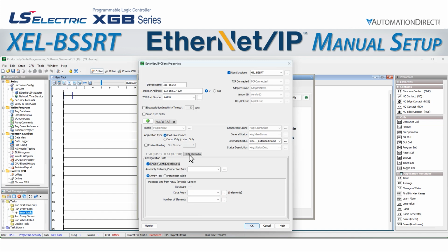The BSSRT does not utilize configuration data, so we can uncheck the Enable Configuration Data box in the Productivity software. If you are working with a scanner software that requires a configuration assembly instance to be specified, use assembly instance 100 and be sure to specify a size of 0.